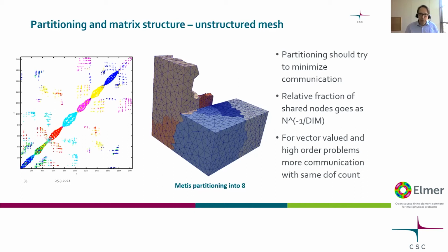And when you have vector valued problems or higher order problems, then you will typically have more of the shared degrees of freedom. And you see also here the challenge of partitioning. So the challenge is to find a partitioning that minimizes the off-diagonal entries in these matrices.